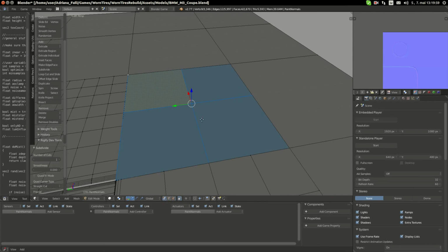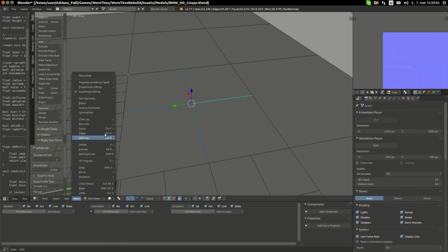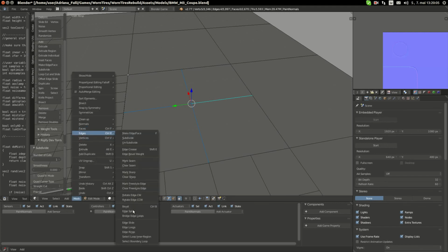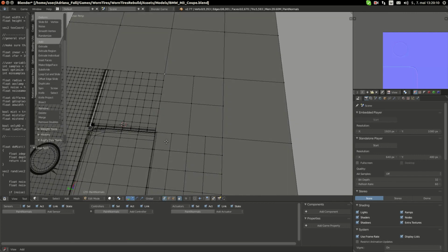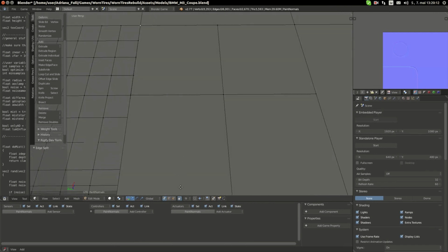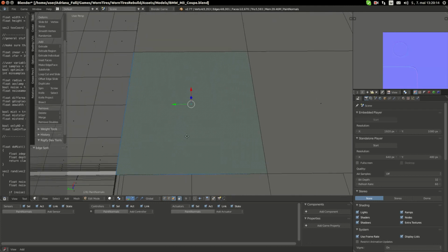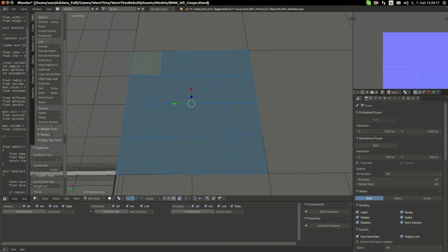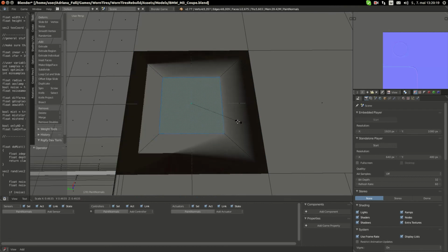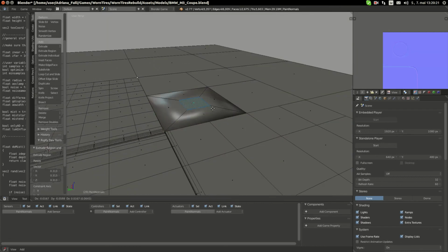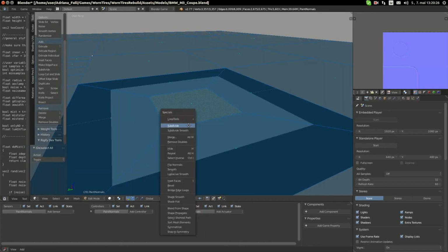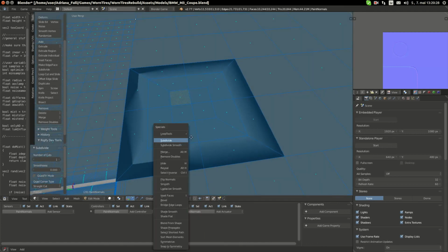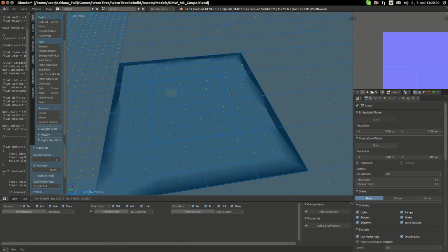So we've got this, and I'm gonna split it like this. So now we've got 4 texture pieces here, twice smaller. And I'm gonna go ahead on this one, add V subdivide V, or maybe better E scale first, and then for all we subdivide. This is gonna be like focused in the center.